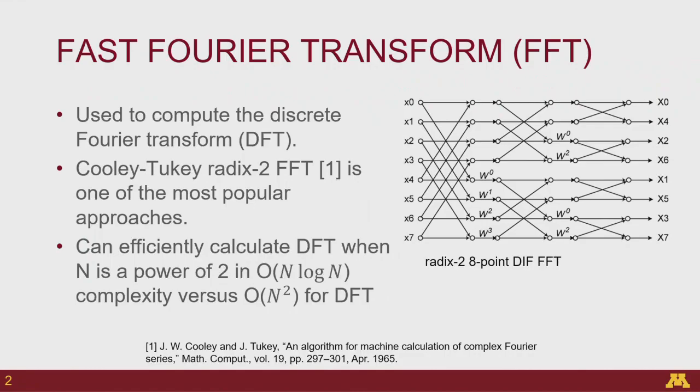Okay, so hello everyone. Today I'll be giving a short presentation on some useful topics for your project. Essentially, I will be walking through some examples of how to code FFT in Verilog, as well as some of the things which you need to keep in mind when you're making these designs. As you've seen in the class, the FFT is a fast and optimized way to implement the discrete Fourier transform, and it's an efficient algorithm which needs only n log n computations versus n square for the DFT when n is a power of 2.